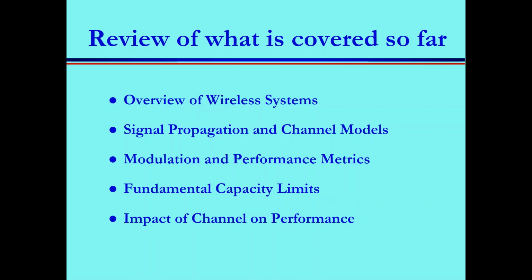We said that when you have fading, you have outage. Besides, we studied the effect of intersymbol interference and how it affects the bit error rate and gives you an error floor. No matter how much you increase the transmit power, you will have a certain error limit that you cannot improve any more. So these impairments of the channel must have some solutions.